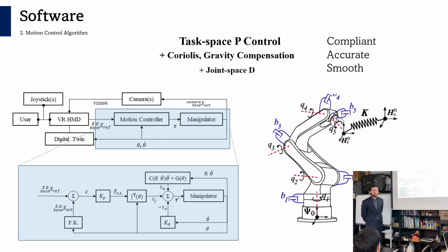But yeah, I completely understand your approach, but the question I want to ask is about the methodology you are using, which is tuning all the B1, B2, B3, B4 parameters. If the end effector lifts some kind of object, for example, or changes its load, then the dynamic characteristics of each motor must be different.